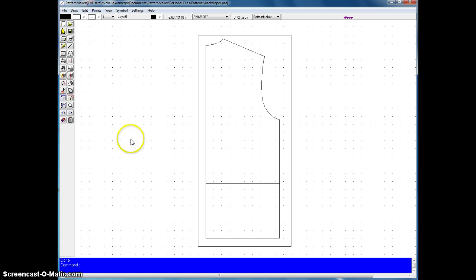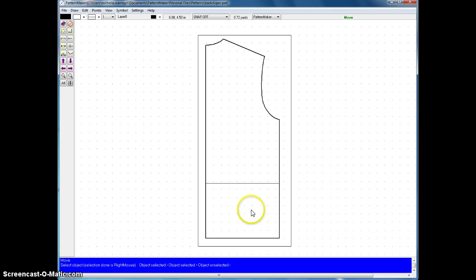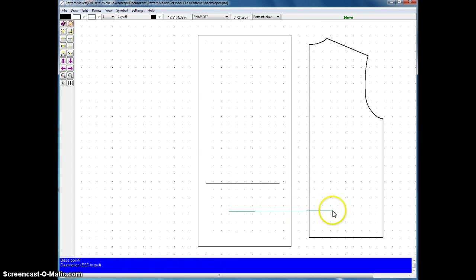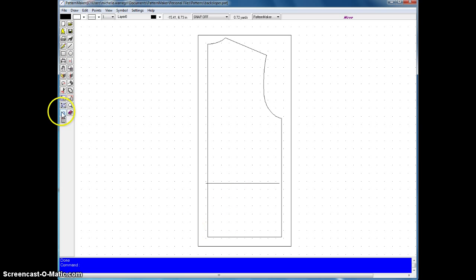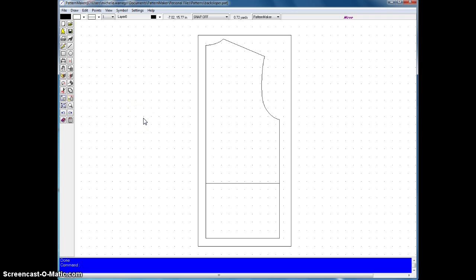But we still have our move tool. I can see that up here because it is in purple up in the corner, and it is asking us to select our objects. And I can select them again and then set my base point and right click, done selecting, set my base point and move some more. I undid or lost that one. Again, undo that and it puts it back in the same place so that you're able to repeat a command again and again with a tool.